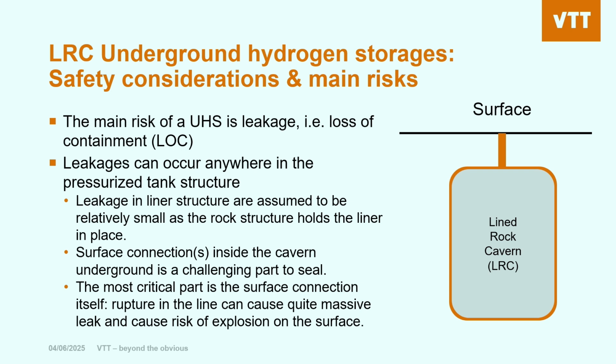The leakages can occur anywhere in the pressurized tank structure, but we assume that if it is in the liner structure, they are at least in the first place relatively small, because there is always firm rock structure behind the liner.